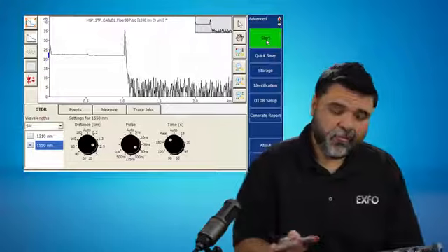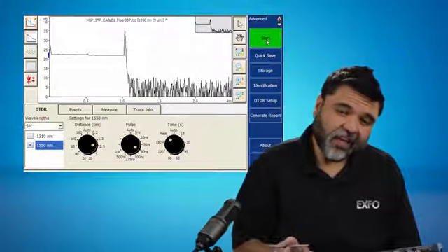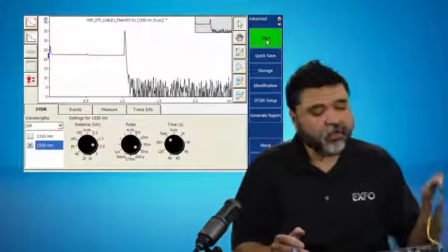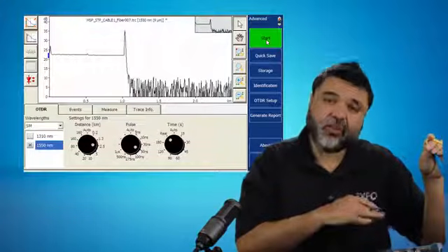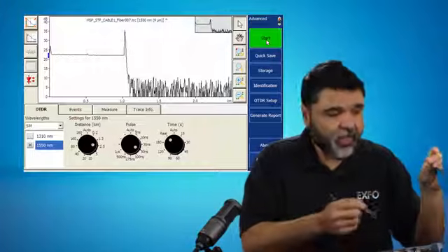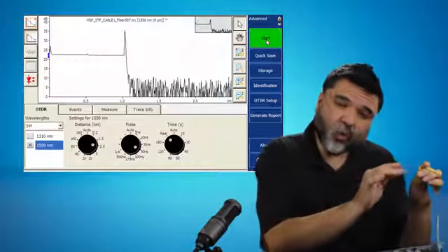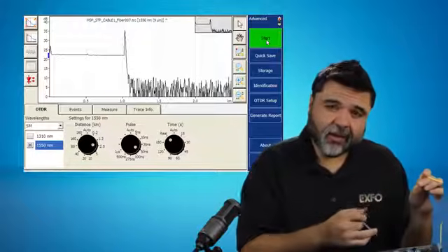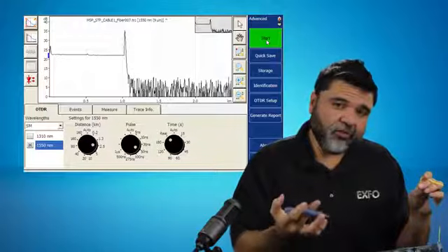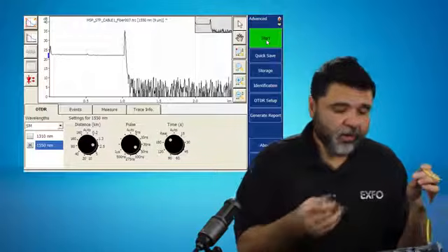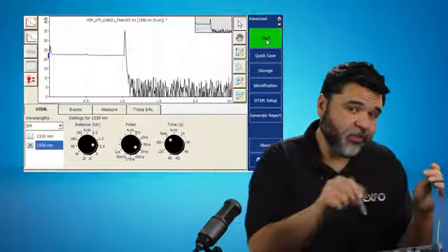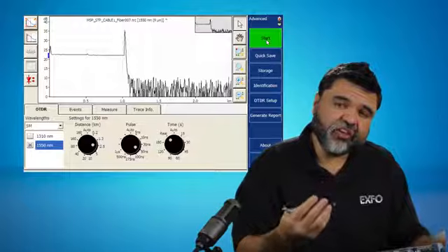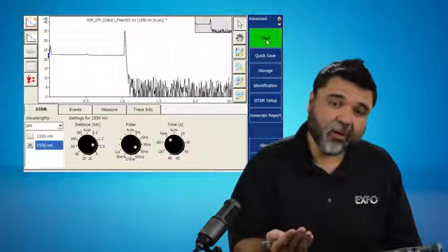And one important point, keep in mind that a macro bend such as the one that I put in the fiber here could be sitting in your FTP tray. This could be sitting up in the raceway inside your central office. If you have an active system that's running and working with a pinch in the fiber, that is basically an attenuator. It's a pad. If you remove a pad or attenuator from a system, you're going to introduce power. So this is about 5 dB of attenuation according to that previous OTDR trace. If I remove that pinch, I've just added 5 dB of power to the system.